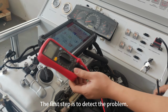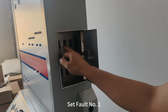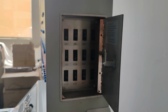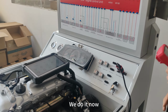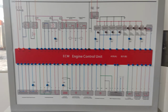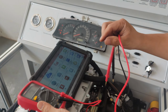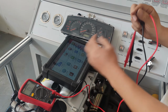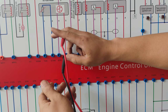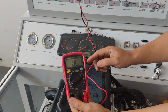The first step is to detect the problem. We are on the fault side. Set fault number E. We do it now. Find the device corresponding to fault 1. Let's measure. On, off. Then twist the multimeter to buzzer. Perform measurements between these two terminals. Turns out its resistance is infinity. Not connected.